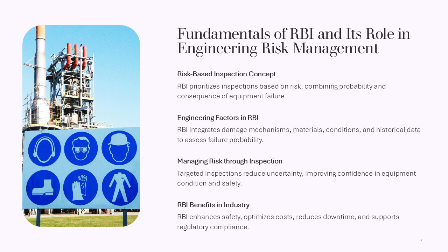From an engineering perspective, RBI integrates knowledge of damage mechanisms, materials, operating conditions, inspection effectiveness, and historical performance. The probability of failure is influenced by factors such as corrosion rates, fatigue loading, creep exposure, and process variability, while consequences consider impacts including personnel safety, environmental release, production loss, and reputational damage. By quantifying or categorizing these elements, RBI provides a risk ranking that guides inspection planning.